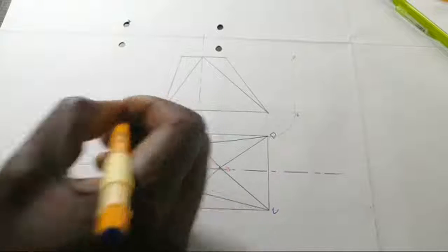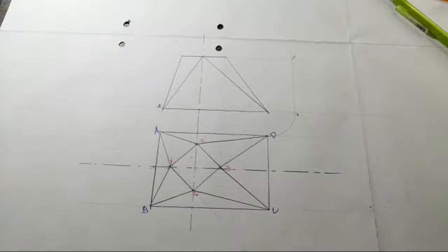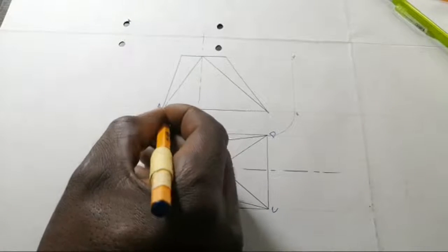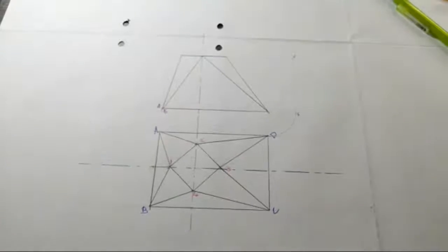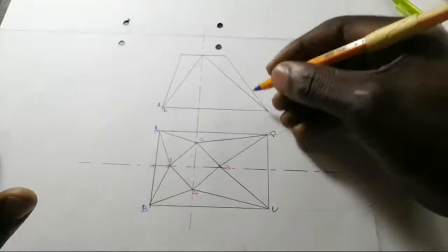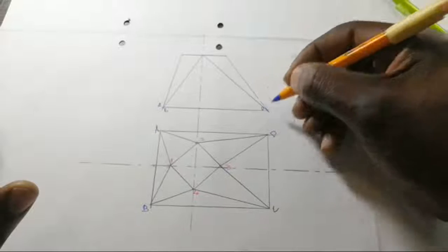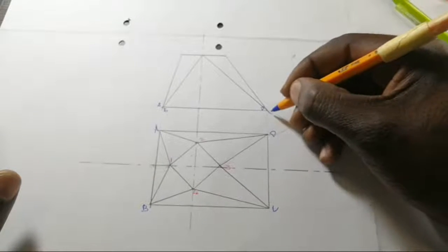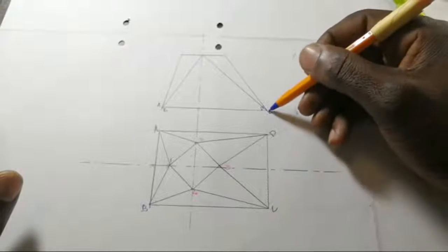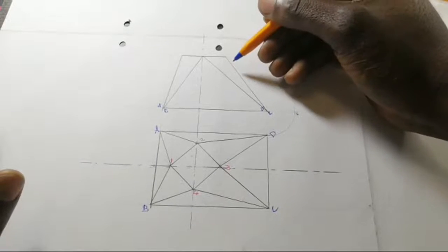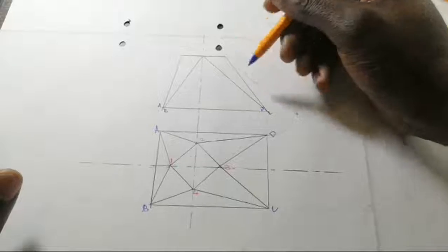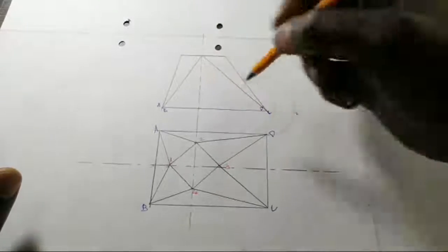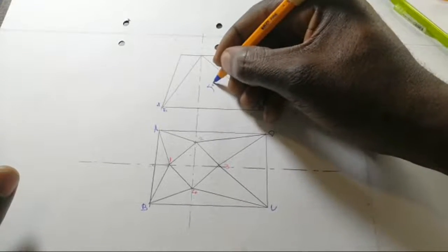So if I am looking for point A in my front view, point A is here. Where is point B in my front view? Is still in the very same point there. And again, D is going to be here. Where is C? In the very same point. So I cannot say my point C is there. Yeah, I cannot say it's there. Because now this is a front view.